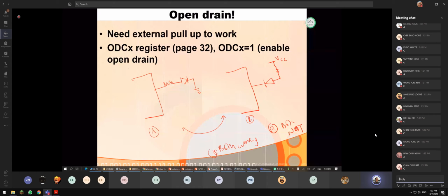Okay, so of course, it depends on the LED. This 25 milliamp is definitely enough. The typical value of an LED is just 10 milliamp only, so no problem. So like this also no problem. I can sink and source the current, no problem. This directly gives enough current to light the LED. So both are working.